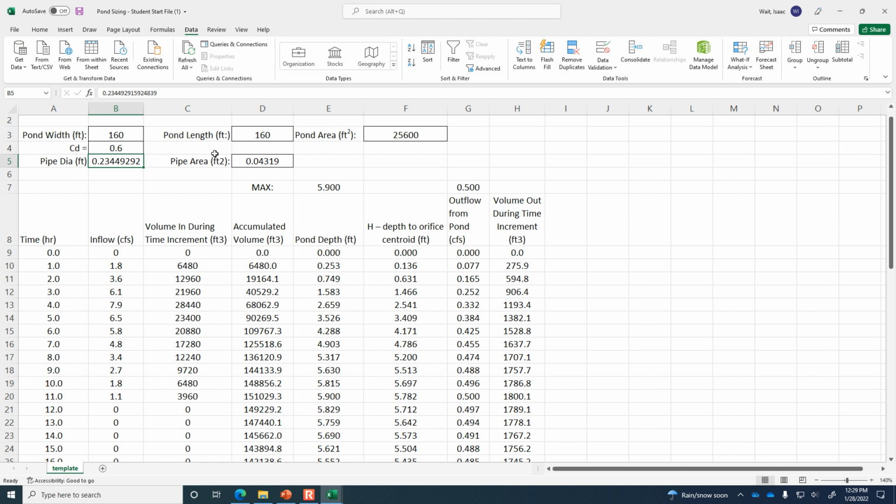So what that all means is probably what we do is put in a 3-inch pipe, because 3 inches is 1/4 foot. And then we'd put maybe a small restrictor plate on the front of it. The pipe itself would be 3 inches, and then it would have welded onto the front of that pipe just a little bit of a restrictor to reduce the effective flow area.